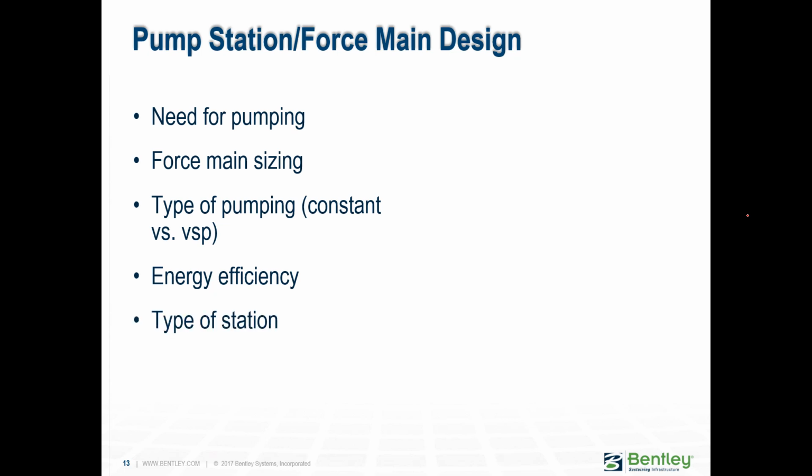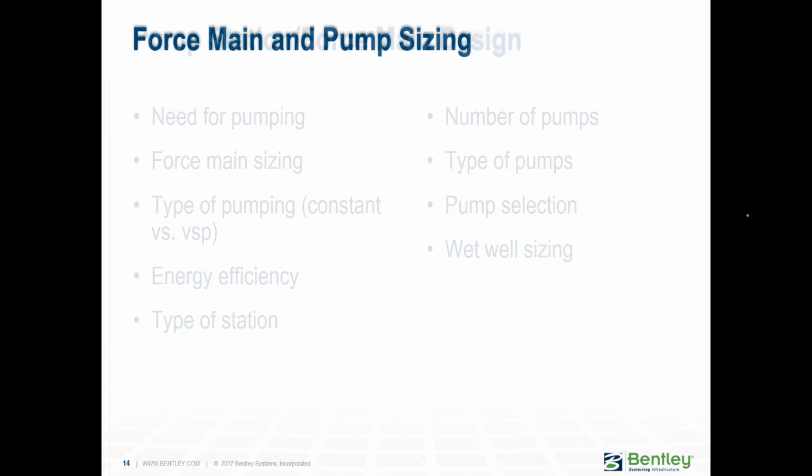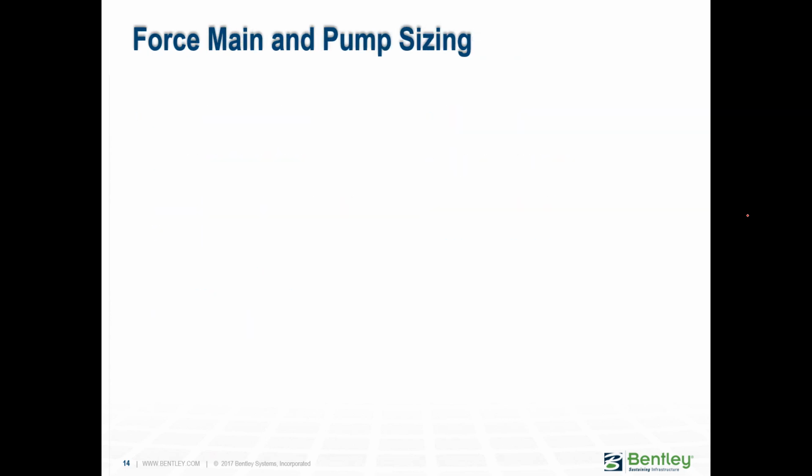So energy costs are really a main driver in the decision of what type of pumping you're going to go with. And what kind of station is it going to be? Is it just going to be a booster station? Are we going to just hold water there for a long time? How many pumps am I going to have? Is one pump enough, and then maybe you just need a backup pump? And how big of a wet well do I need? So all those details can be worked out, just in that order.